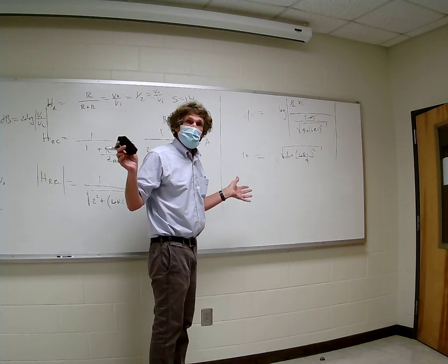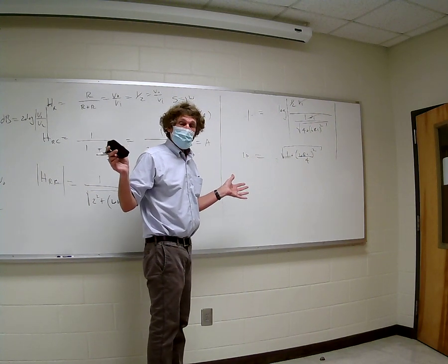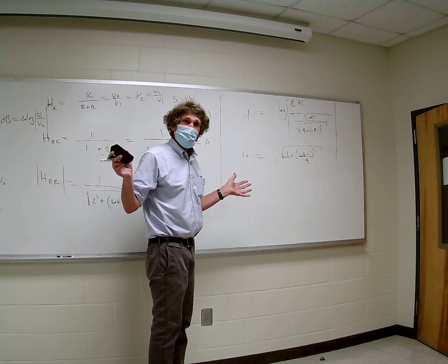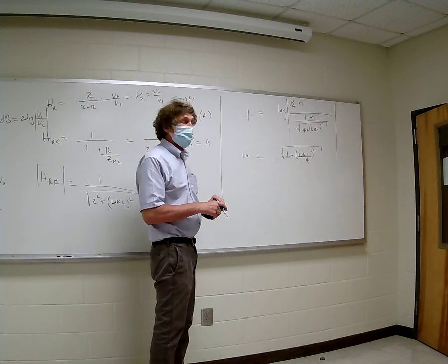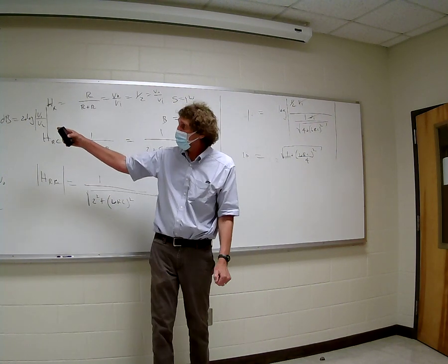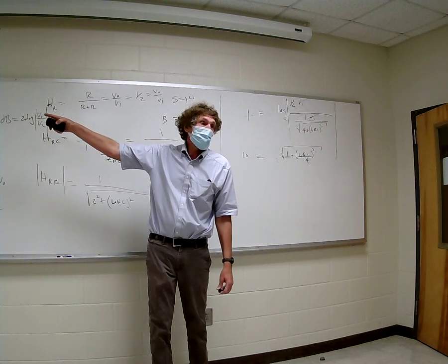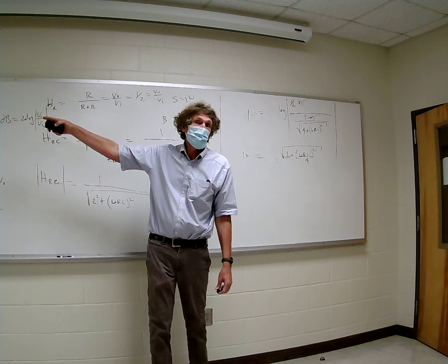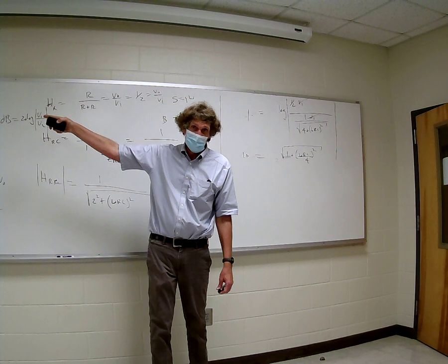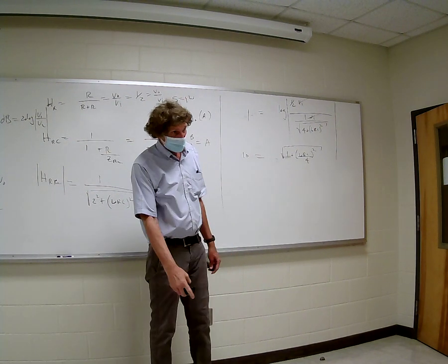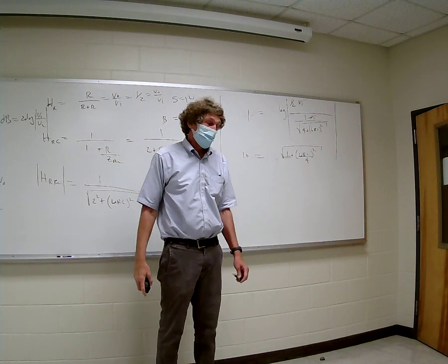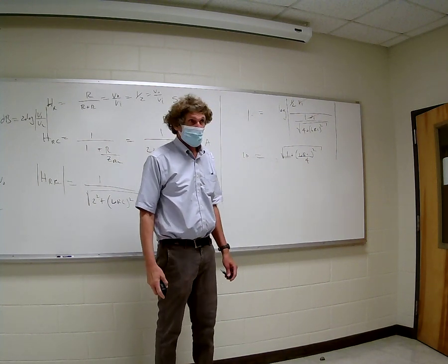We still haven't got omega, or C. Omega is going to be the fifth harmonic. Fifth harmonic, no problem. We know F naught is 1 over T, and that's equal to 10 megahertz, so then omega naught would be 2 pi times 10 megahertz. And therefore, the fifth harmonic would be 5 times 2 pi times 10 megahertz.